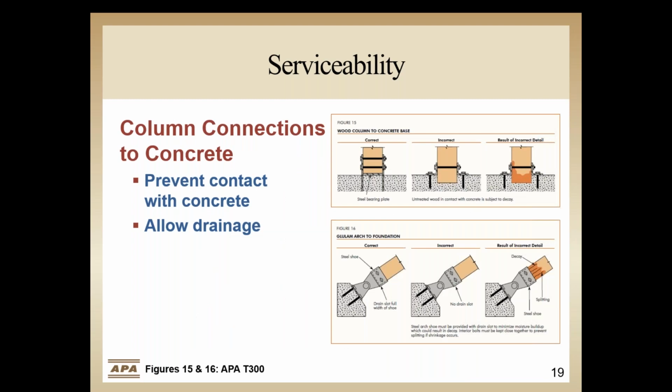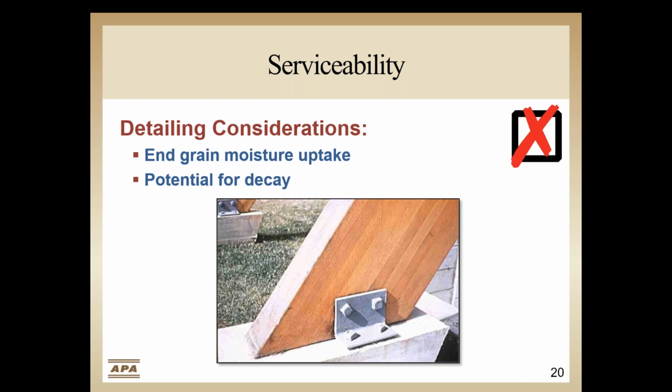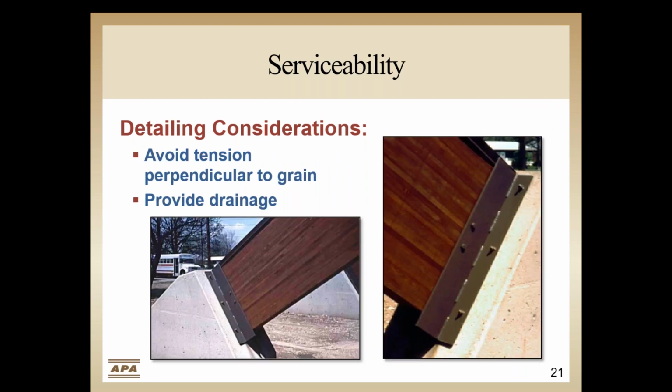Another consideration is using wood in proximity to other materials. Concrete is porous and wicks moisture. Good detailing will use separators like base plates or standoffs, etc., to permit wood to be used without direct contact with concrete. One might think that this solution works. However, the flat concrete surface may allow the wood to contact standing water even if a vapor barrier is installed at the base. It is not encouraging to the long-term welfare of the wood.